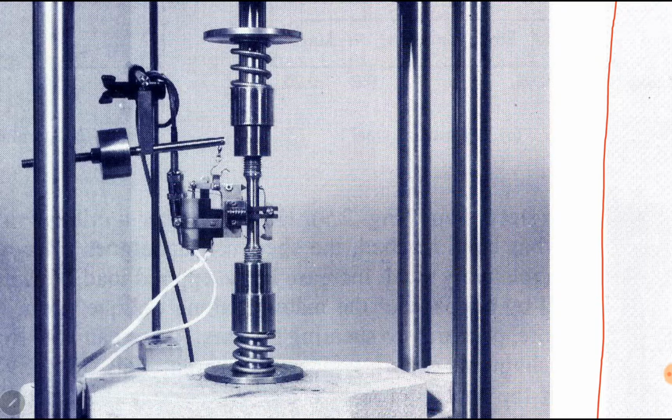It will simply deform elastically, and after we remove the load, it will come back to its original position. So most of the designers think that material will not fail if we do not exceed the loads beyond yield strength. But if the loads are repeated loads, or they are cyclic loads, the material may fail even before the yield limit, which is sometimes unpredictable. So then comes fatigue properties of the material.